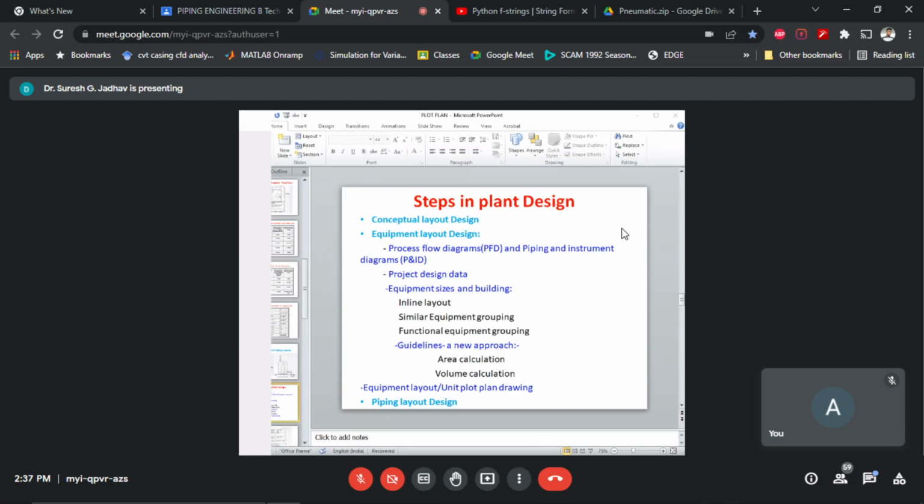The space allocation is there for all the basic plant requirements, such as laboratories, offices, storage, etc. Access for operation, maintenance, and construction is provided for. Control rooms and motor control center rooms are also planned. The basic size of the building or structure is worked out. The resultant drawing is the conceptual layout.